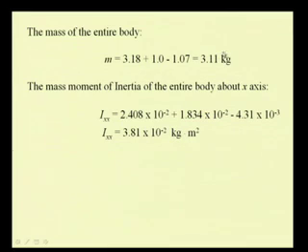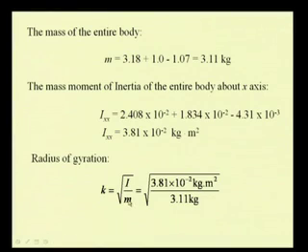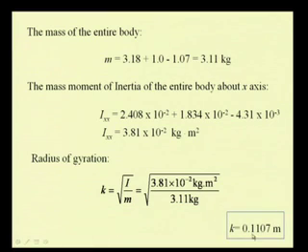So, we know the total mass of this machine element, we know the total second moment of this machine element with respect to the x axis. So, now we can determine the radius of gyration as root of I by m, which is this quantity. We find this to be 0.1107 meter. So, this example again illustrated how to compute the second moments and the application of the parallel axis theorem, and also we determine the radius of gyration. So, we will continue the discussion.